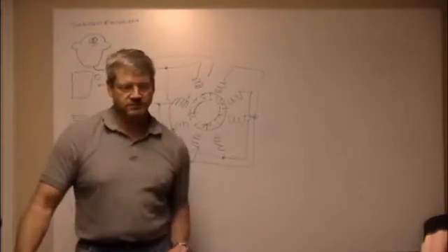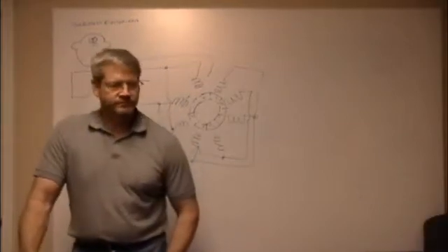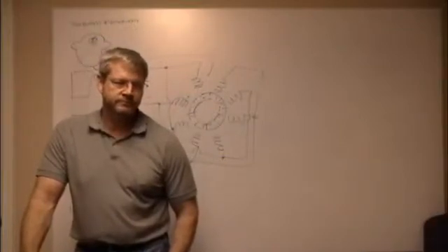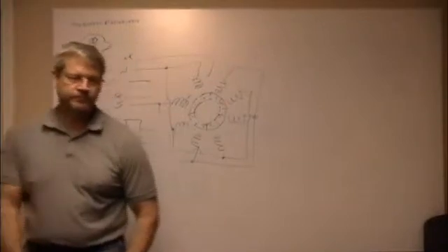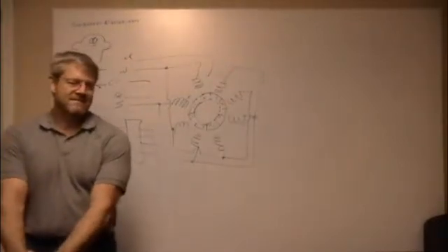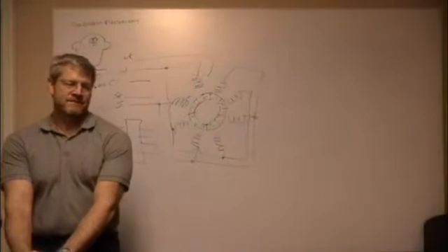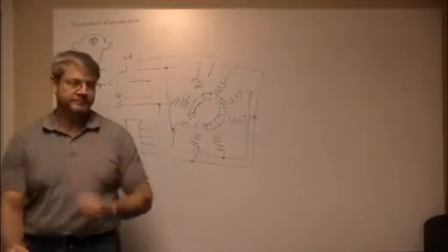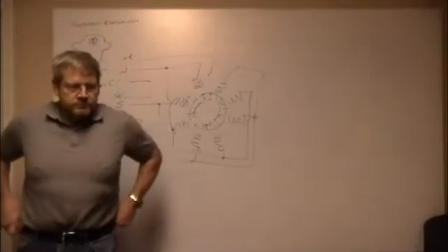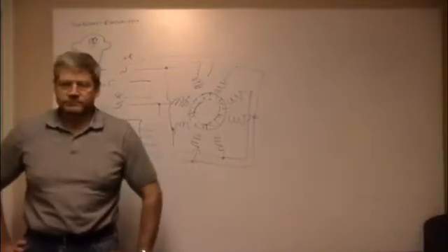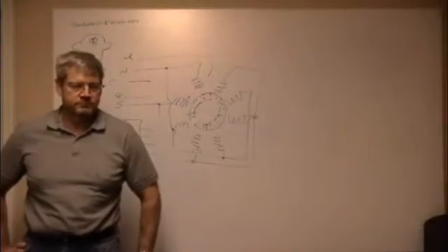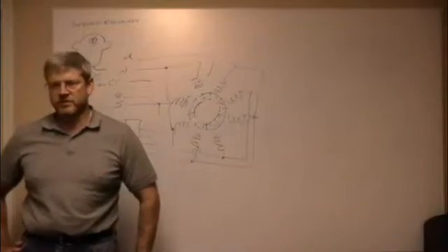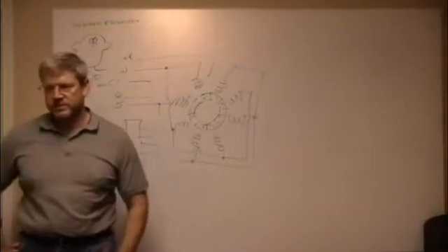3D printers tend to use a stepper motor on X, Y, and Z, and on mine, X and Y are belts, and then Z's a lead screw, or whatever they call it. But then you also have a stepper motor feeding the filament in. Since it's a known quantity for what each of those steps are, I can move 1 micron this way, 1 micron that way, or up and down. You can move tiny amounts pretty precisely. You can't get that precision out of one of these kinds of servos.